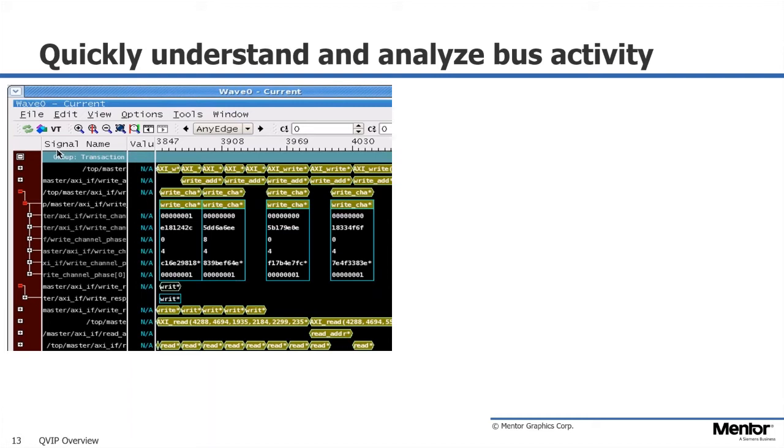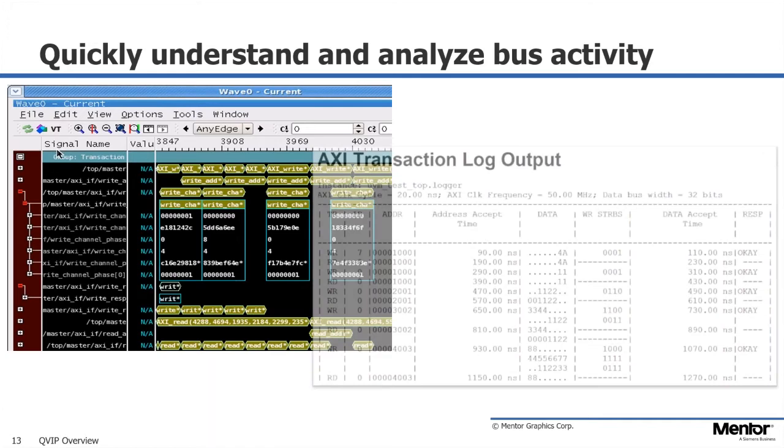By having the monitor in there, it can monitor the activity on that bus and turn it into, over this amount of time, a transaction with these parameters happened. That is a hell of a lot easier to debug than trying to look at the 6,000 transactions on the 2-wire bus to figure things out.